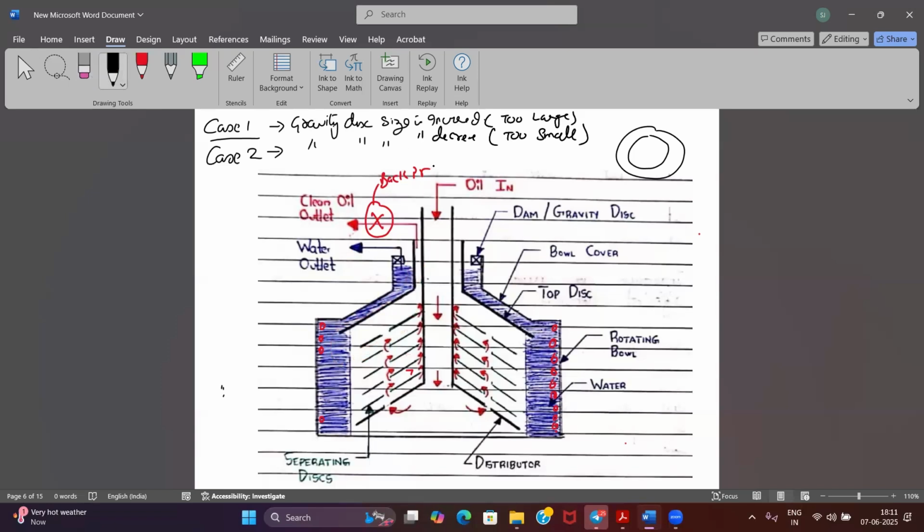If everything was okay and running in this state, how much back pressure do you maintain? This is the range, from 1.5 normally to what I've seen till now, 2.5. In this range we are varying; it depends upon the purifier, depends upon the feed, and depends how much you want better cleaning. The more the back pressure, the better the cleaning will be, but you have to simultaneously reduce the throughput also. So this is the throughput where the oil is coming in.